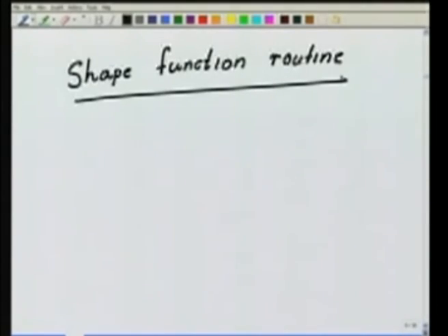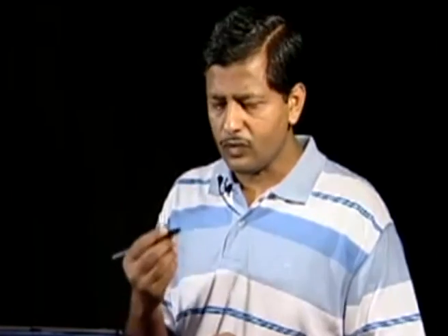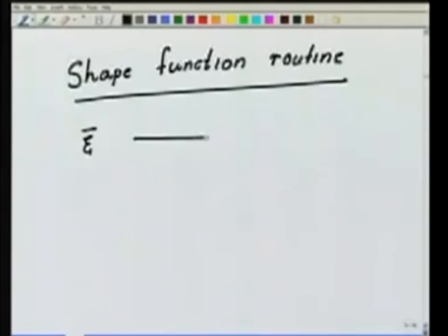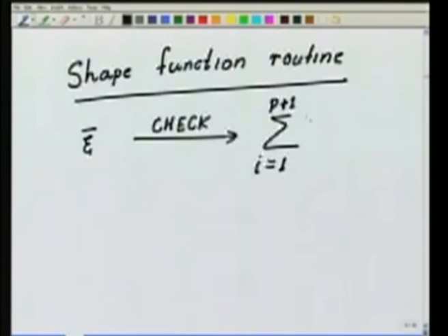What are the checks that one can do? For the given psi bar, check whether the sum of all the shape functions is equal to 1 or not.